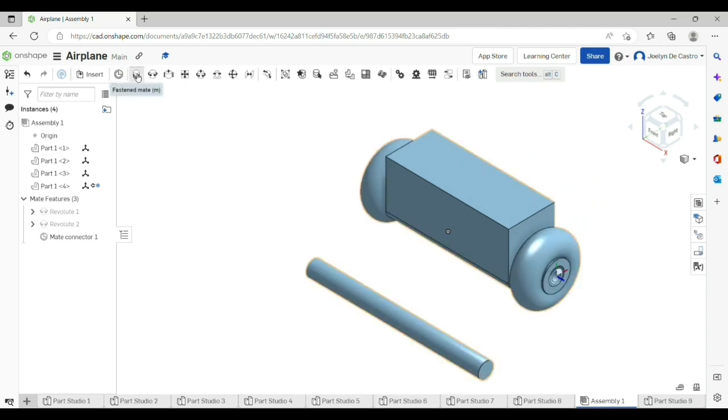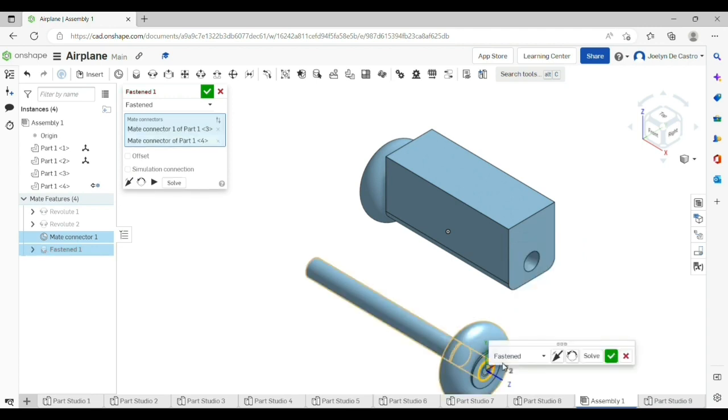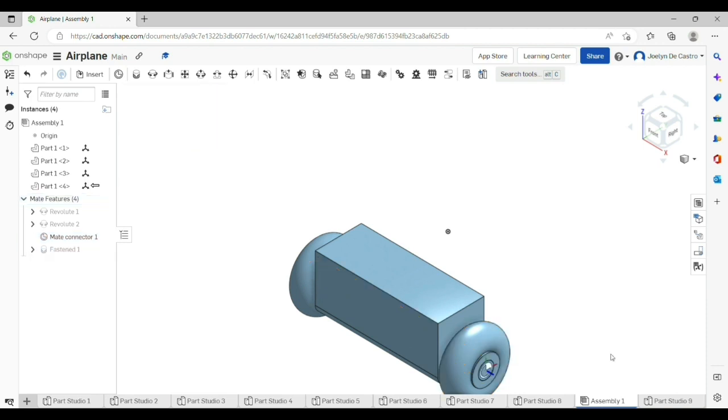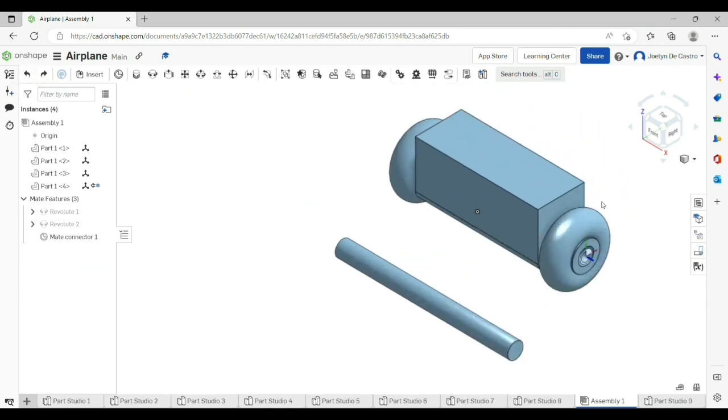Use extrude and choose that sketch. Go in the other direction and go up to the next face to use the outside edge of this wheel as the defining length of the part. So use the information from my assembled pieces to help create this part. Accept that and the axle has been created.